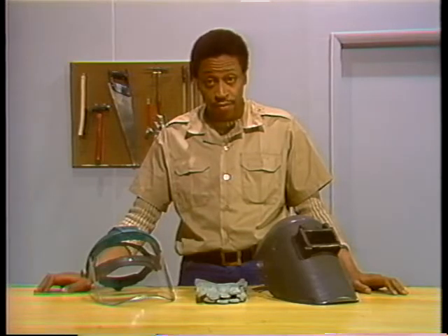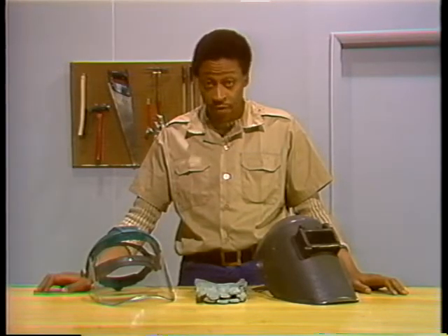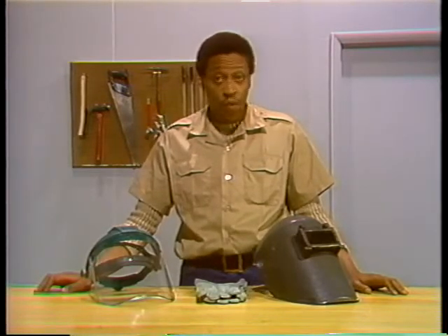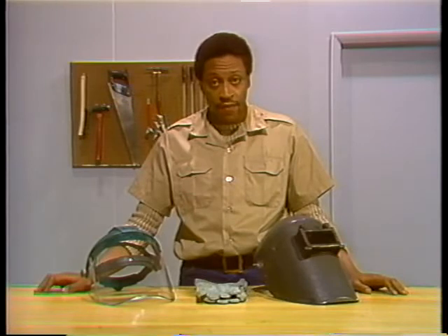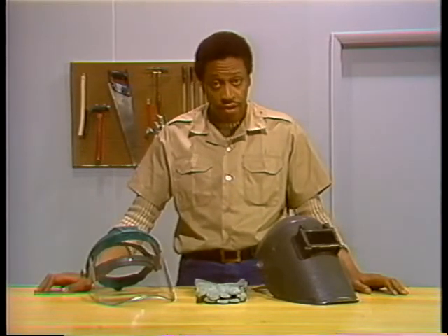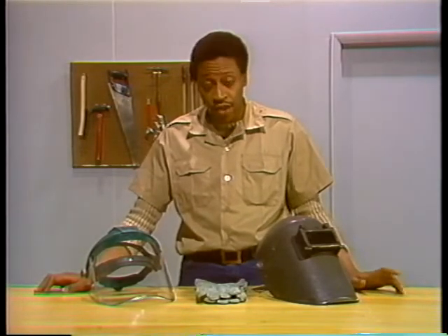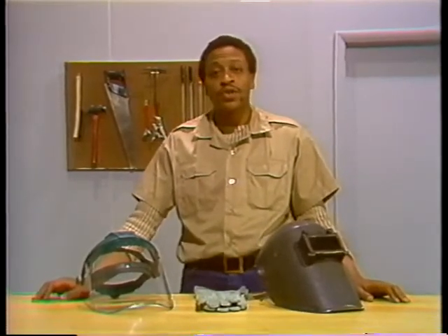They're used when the edges of a thick-lipped rupture cannot be forced together. Window repairs are also used if pieces of the tube are blown away. Generally, window repairs are most useful for fixing failures in large tubes. As with other repairs, the first step is to familiarize yourself with the procedure. Read over the written instructions or talk to an experienced welder.